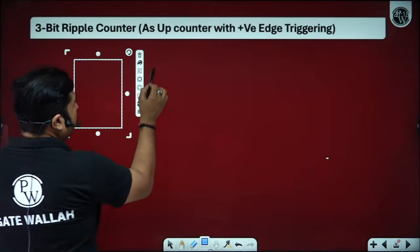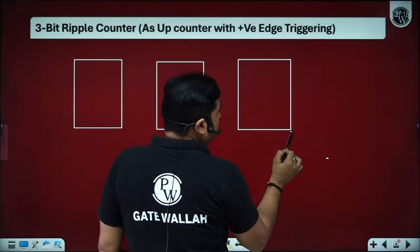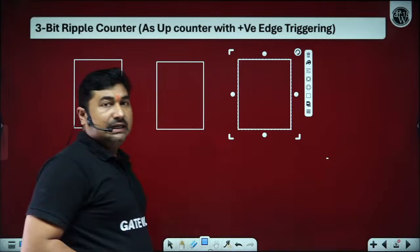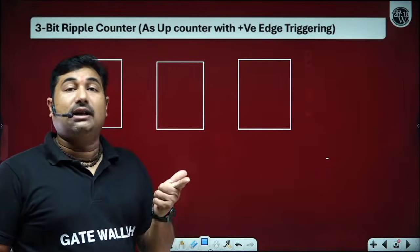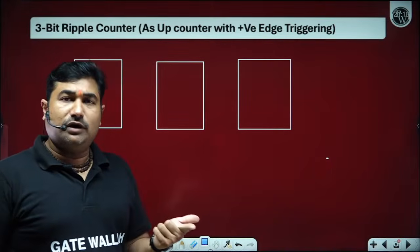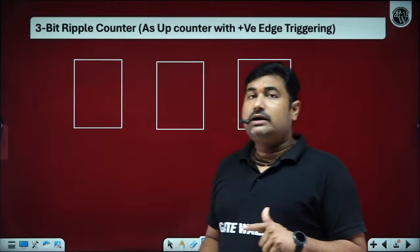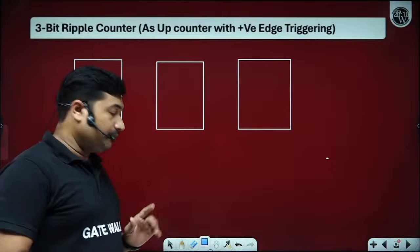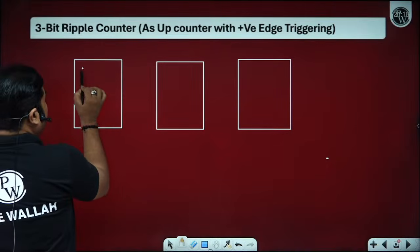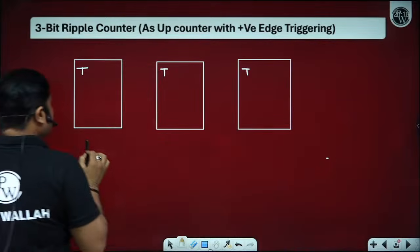Either we can use JK flip-flop or T flip-flop, because in a ripple counter flip-flops operate in a toggle mode. A JK flip-flop toggles when both J and K are 1, or a T flip-flop toggles if T equals 1. So I am going to use a T flip-flop.